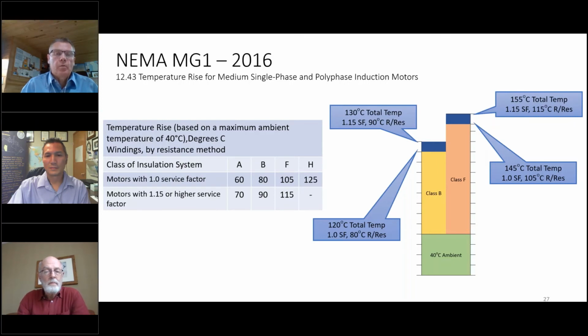We talked about this offline in the RATS committee, but you will see nameplated information, like the switching frequency and temperature rise. So generally speaking, depending on the topology of the VFD, some VFDs will add a lot more heating to a motor winding than others.